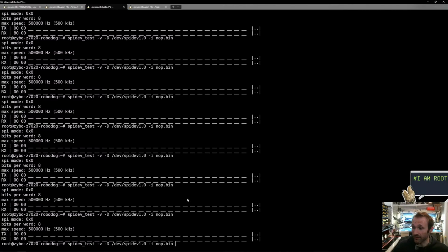The only reason I know to suggest that is because I've seen other SPI designs have a lag to them, where each one of these is being clocked in on a rising edge of a clock on the peripheral device. So I'm guessing maybe it takes a couple clock cycles to read in the command and then a couple more clock cycles after that to give you the response. Or maybe it just gives you the response in the same clock cycles as it's getting in the commands. That probably is it, so this might not help, but I'm gonna try it.